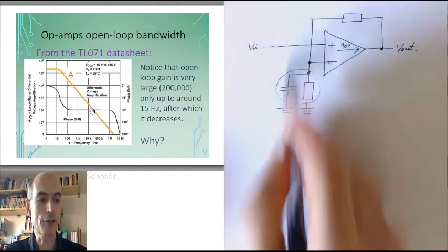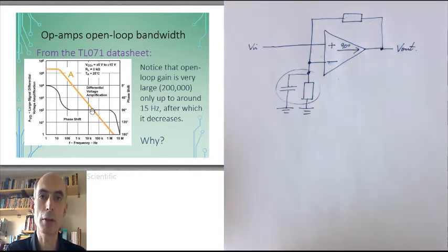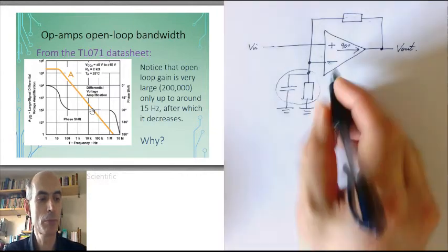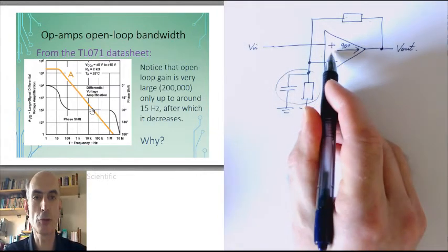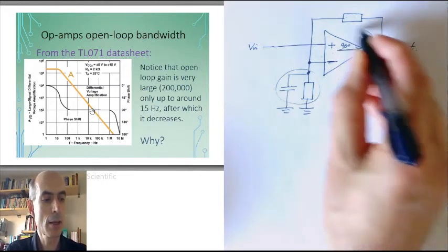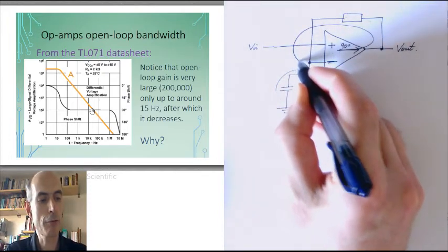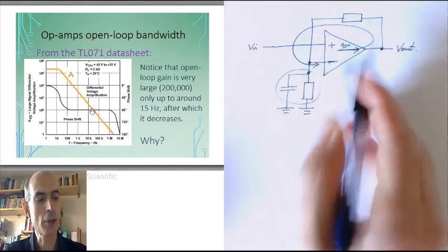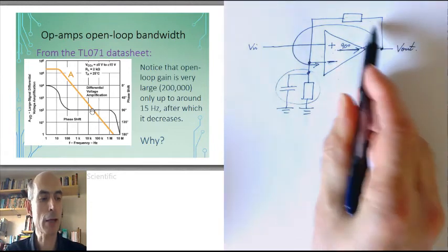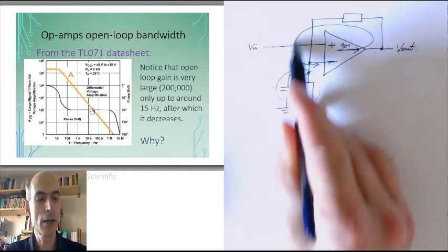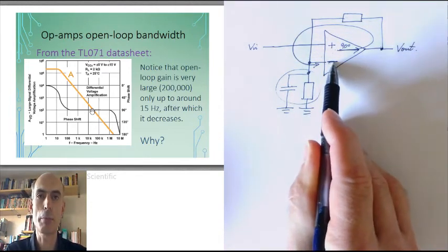There are other effects around in the op-amp as well, all of which can increase the total phase change between the inputs to the op-amp and the feedback signal that's come all the way through the op-amp, back through the feedback resistor there and down, and is going back into the op-amp.